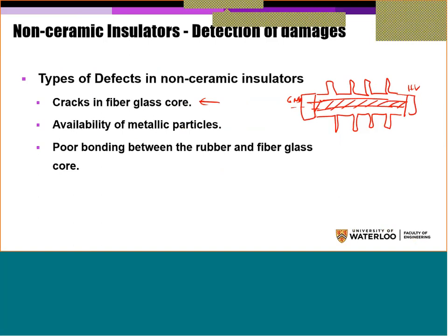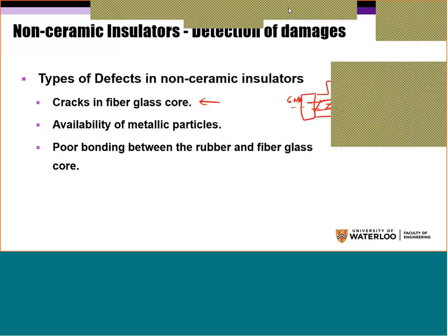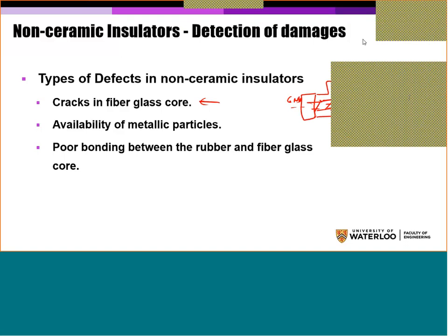Another question, let me answer. Would it be a safety hazard if you misclassify? No, there is no safety issue here. You want to classify the insulator. If you misclassify HC1 as HC2, there is no big deal. It's still hydrophobic. It's not the exact class, but it's a close class, so that's good enough. There is no safety hazard here.